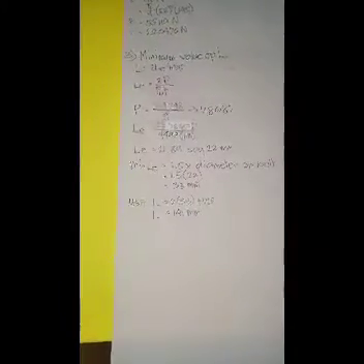Then bearing capacity of bolt R is equal to A sub p times F sub p. So our answer is 189,784. There is no need to write the solution since it is the same as number 1. Same answer for the bearing capacity of bolt. The tension is the same, 759,137. Then we choose the lower value to get the safe capacity. So our safe capacity is 220,476 Newton.